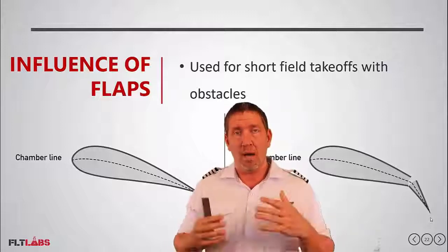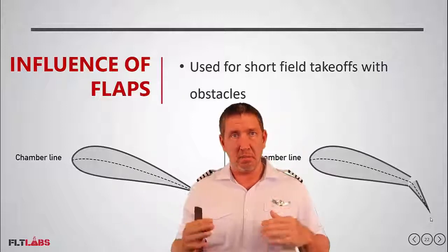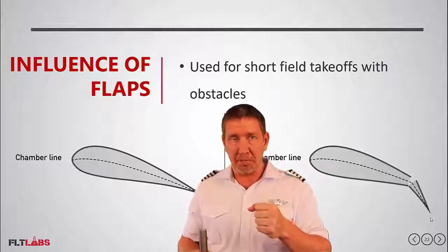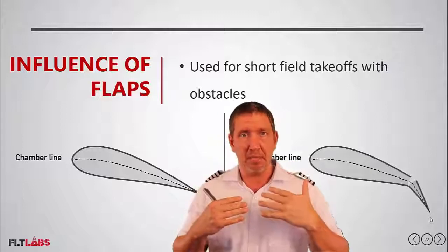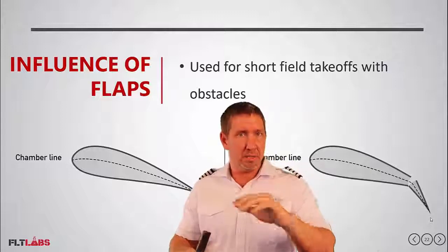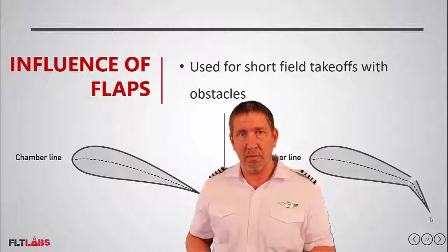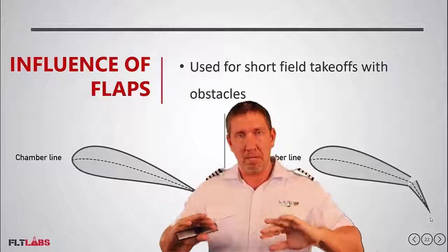So what I do in this video is speed check, flaps up selected, and then when those flaps are moving, what I'm actually doing is applying aft pressure on the control stick so that I can maintain my speed. I don't begin to accelerate and the nose doesn't lower so much. So let's take another look at this video and we'll pay attention to what's going on when the flaps go from takeoff to up position.